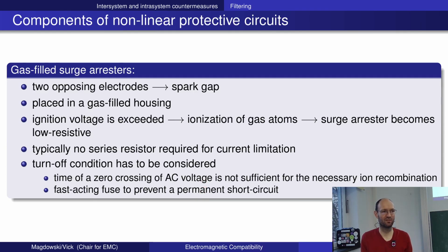There's a chance that a certain device, instrument, or installation is hit by lightning every 1 or 2 years, and if it is hit, this gas-filled surge arrestor will protect the device, still the fuse will be broken and someone needs to go there and replace the fuse. Otherwise the device will probably not work anymore, or the protection is not effective anymore.